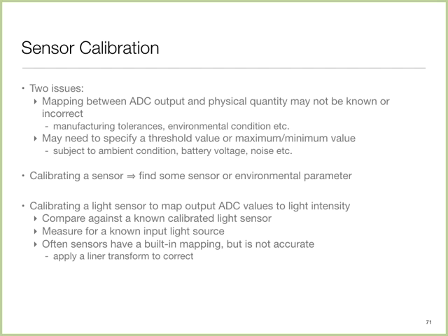Sometimes you have to have special procedures in place. Sometimes sensors have memory, so that over time they begin to drift and their calibration parameters change. For example, magnetic sensors, which exist on our phones, are notoriously subject to that. Over time they begin to saturate.